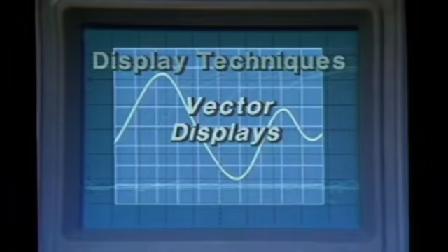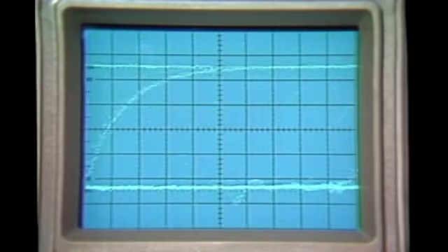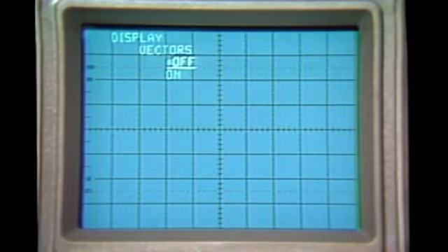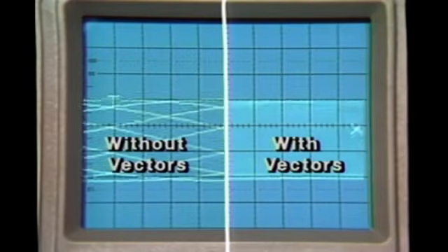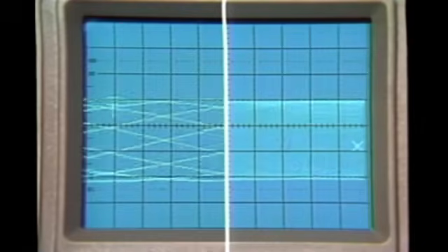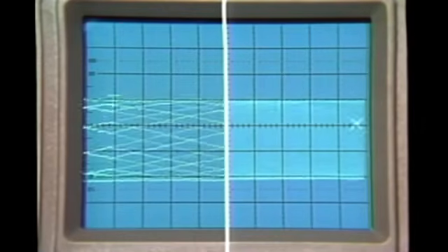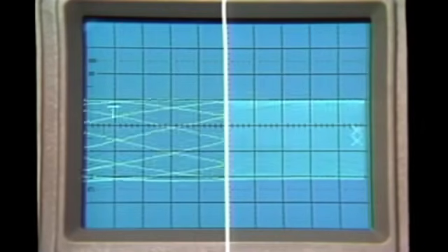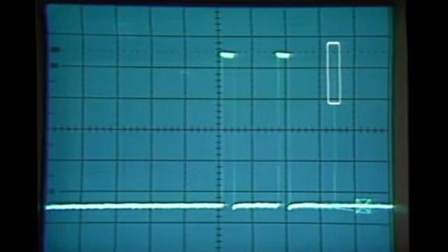Perceptual aliasing in dot displays is easily corrected by using vectors. Vectors provide a better indication of the wave shape, and we don't need as many sample points to actually show the wave shape. When used for reconstructing sine waves, a vector generator requires only 10 data points per cycle of the sine wave to reconstruct a recognizable display. Vector displays also make glitches more visible by connecting every data point and preventing a single dot, far from the rest of the waveform, from being overlooked.